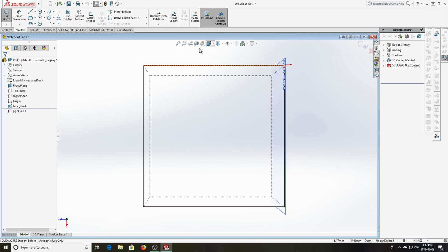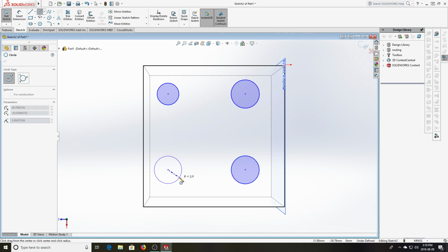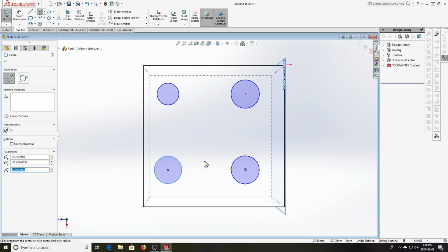And now with this sketch, I'm going to draw some circles. Here, here, and you'll see that it's trying to help me maybe align the circles. So if I slide around and drag my mouse, I'm not pressing any buttons, the little pencil for the next circle is picking out what are called snaps. In this case, if I slide it there, it's picking out snaps that are aligned with the other two circles. And I've just been right-clicking, and those are my circles.